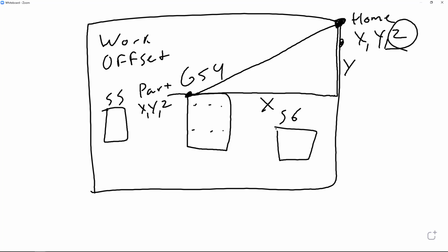For the most part, there are times to set the G54Z. But you still have to take into account the tool length because that changes per tool. But let's look at that right now. So I'll clear this, and let's take a look at this from the front view. So what we're talking about now is going to be G43. This is cutter comp in the Z. So we'll talk about cutter compensation later, but this takes care of tool length offset, or TLO.